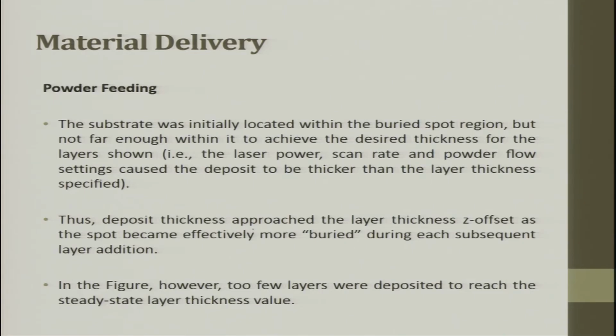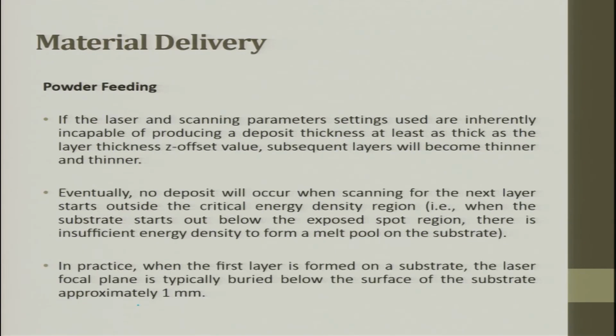Thus, the deposit thickness approaches the layer thickness Z offset as the spot becomes effectively more buried during each subsequent layer addition. However, too few layers were deposited to reach the steady state layer thickness value.